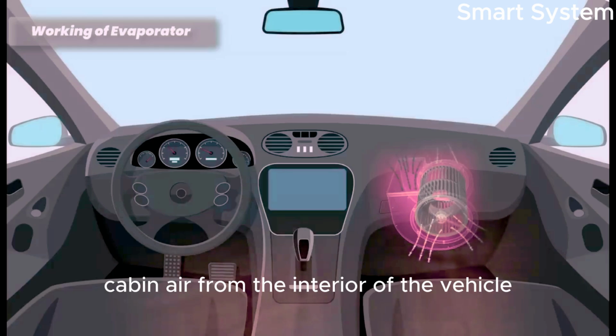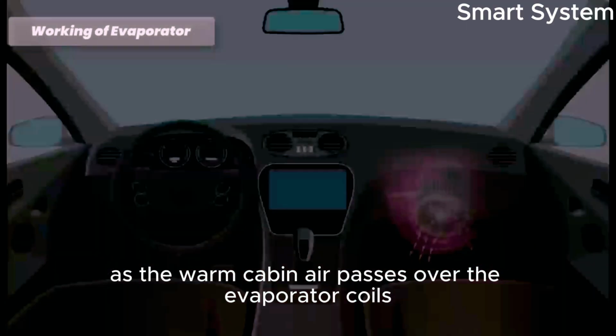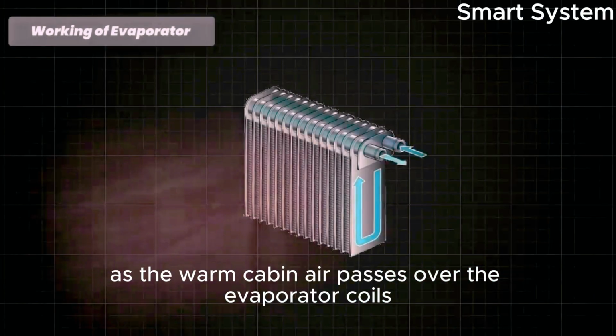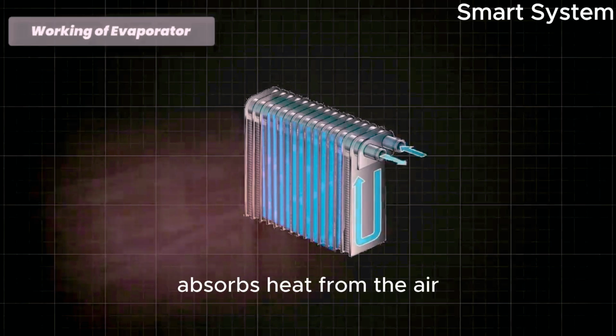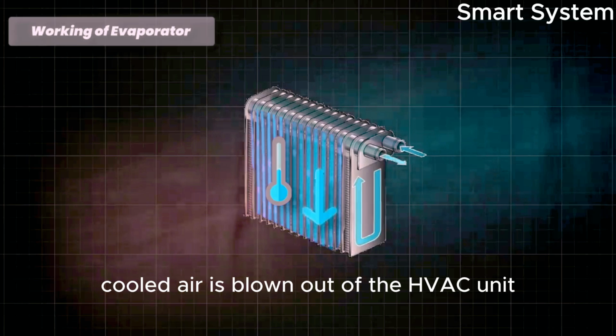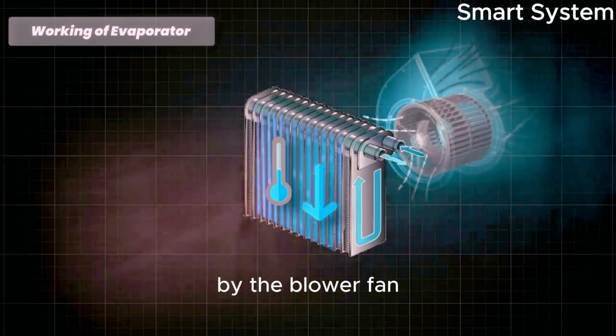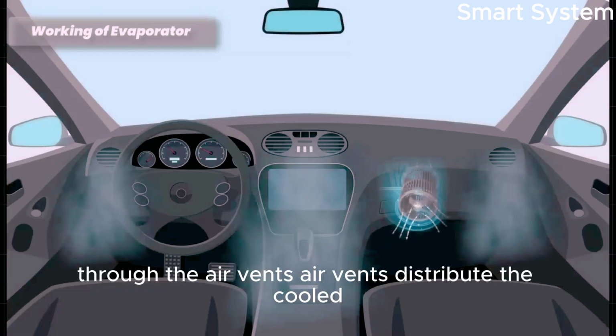Now warm cabin air from the interior of the vehicle is drawn into the HVAC unit by the blower fan. As the warm cabin air passes over the evaporator coils, the refrigerant inside the coils absorbs heat from the air and makes it cooler. Then the now cooled air is blown out of the HVAC unit by the blower fan and circulated into the vehicle's cabin through the air vents.